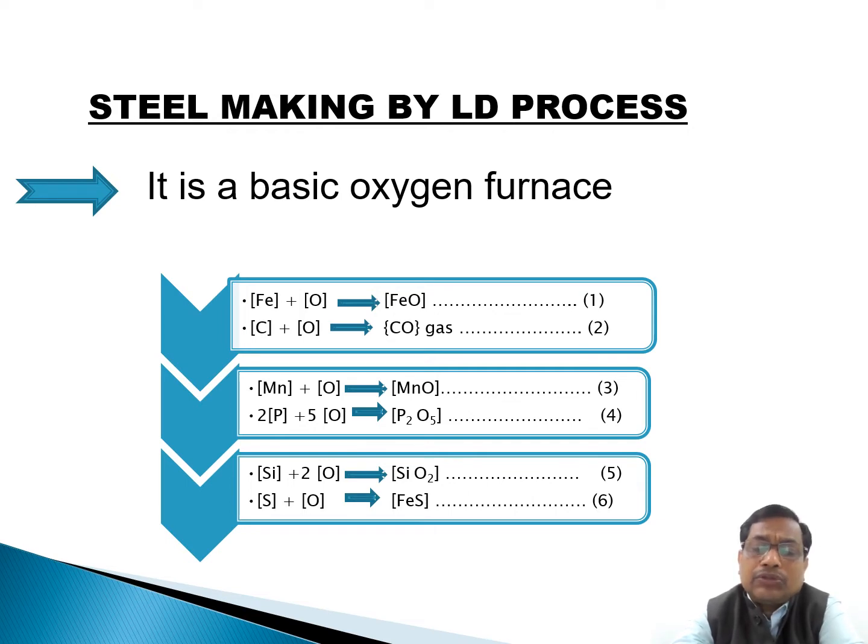So in order to get this quality of steel, what do we have to do with the pig iron? That is a big question. We have to take out these impurities. How can we remove them? We can remove these impurities in the form of slag. In order to form a slag, we have to convert the impurities to their oxide state. That is the primary step so that they will move towards the slag, or form the slag. That means they have to oxidize.